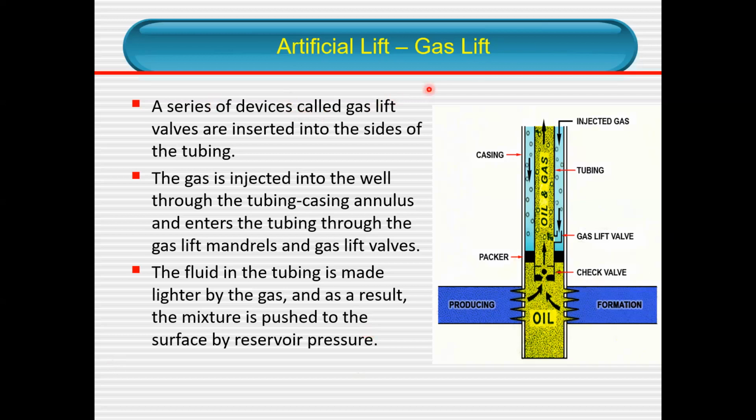Why gas lift? A series of devices called gas lift valves are inserted in the tubing. Gas is injected into the well. Okay, let me just explain how this gas lift works. Gas is injected through the casing, and you have gas lift valves such as this.